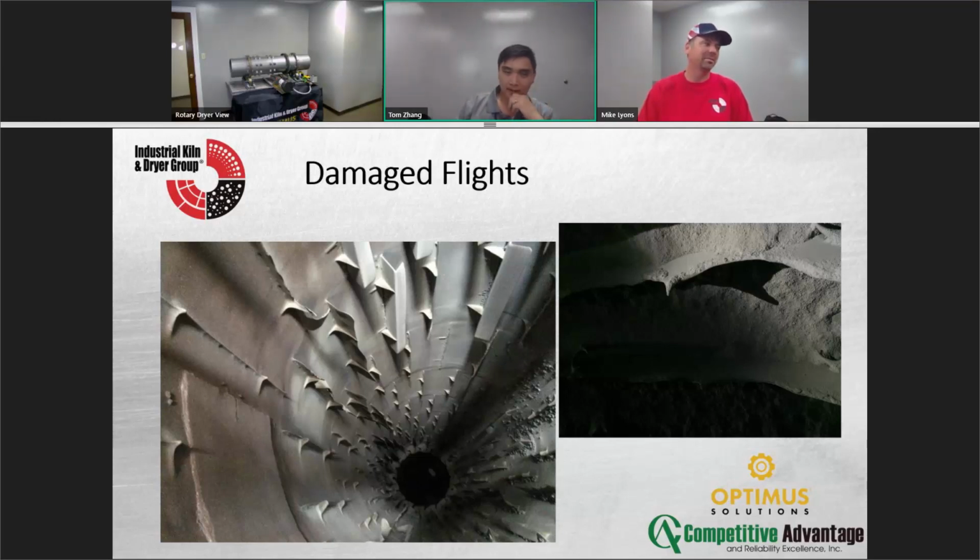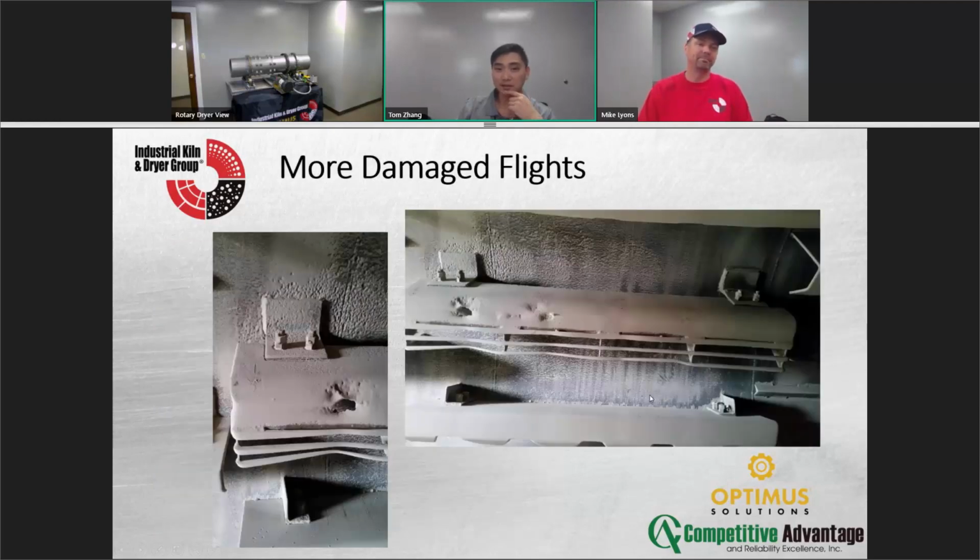So I went down there, went inside, and I was like, "Hey guys, you need to put some flights in." And they're like, "No, we don't need to do that. We need a new burner." I was like, "You need to put some new flights in, because if you have something like this on a dryer, it's not going to fail, but you're not moving the material at all. Actually, this one's a different unit, but you got."